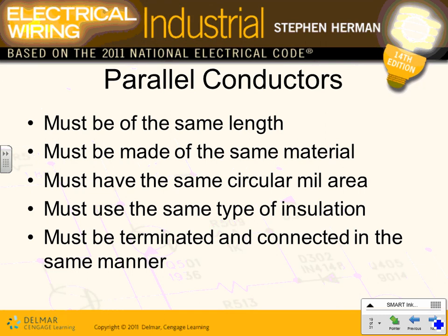Okay, here's what I would like you guys to do for parallel conductors. If you don't know this right now, please be aware of it. With the parallel conductors, they must be the same length. So let's just say 100 feet. All of them must be made of the same material, THHN. Must be the same area, 4/0. And must have the same type of insulation.